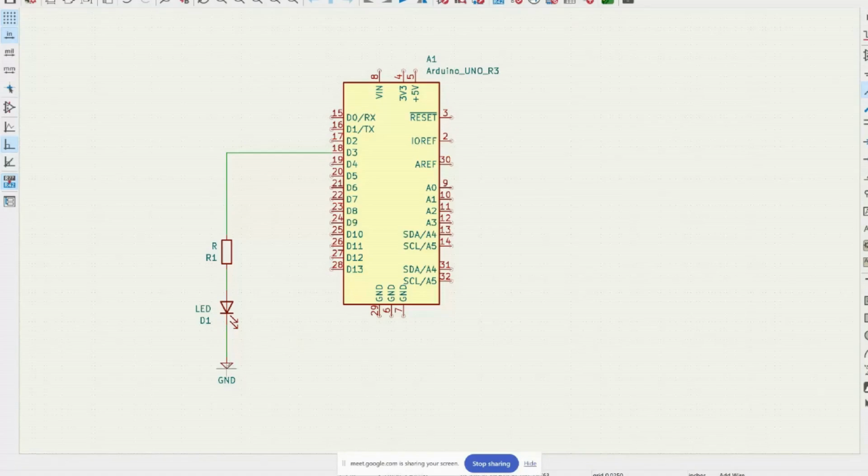So the first answer was that this is a ground global pin. That is exactly right. I'm going to talk a little bit more about that in a moment. Another gentleman over here said there is no current path. Because the Arduino ground is not connected, there's no place for that current to flow back to the Arduino. So we have to connect the grounds on the Arduino.